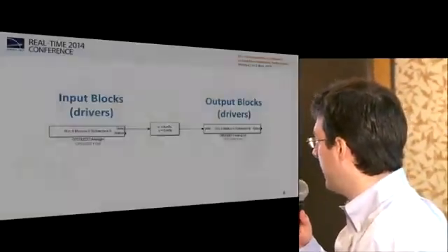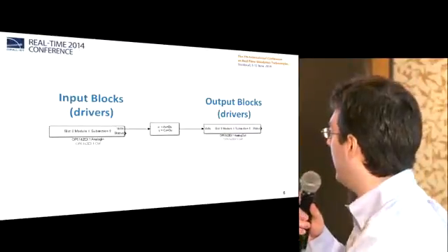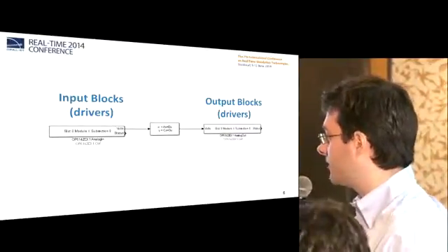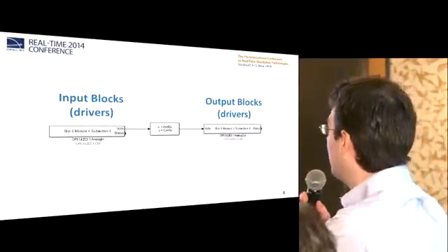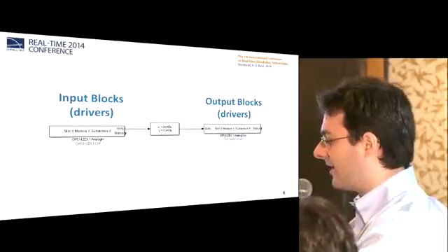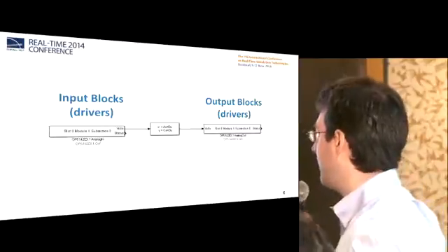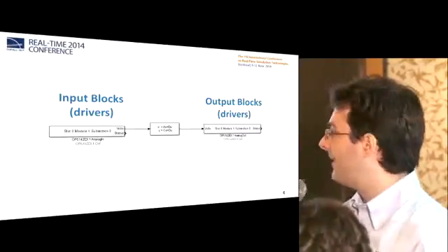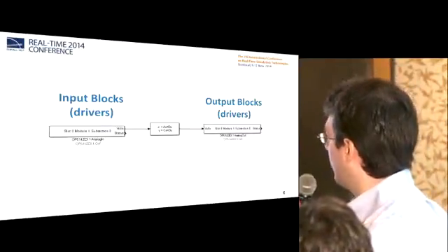So the first thing is, given the actual model, originally somebody built that Simulink model with a PID, with an input and an output of the expected data flows. To that model, we'll be adding OP5142 blocks to basically import inside of the model the S functions that will actually provide the data coming from the hardware and send the data back to the hardware. But really, that's not enough. Oh, we're going to have the inputs, my apologies, and the outputs, of course.